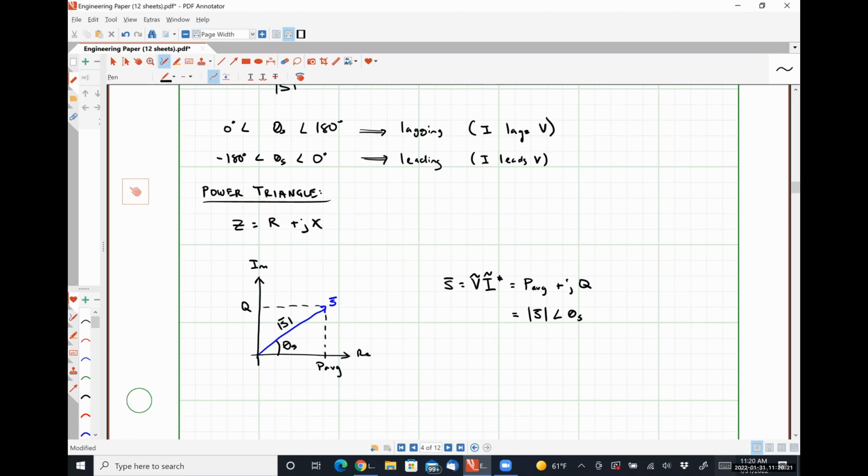So if the load that you are designing your system for is operating at a very inefficient power factor, the current that you're designing for is actually probably a lot larger than you need, which means that they have to use either larger wires, which contain more copper and are therefore more expensive, or the same size wire, but with a better temperature regulated sheath or insulator around it, which is also more expensive.